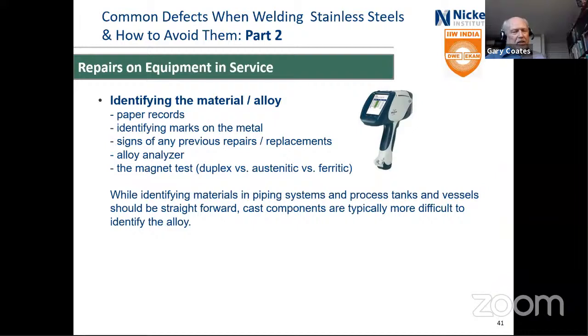And especially with cast components, a lot of cast components don't actually have a standardized grade name on them. They'll usually have the manufacturer's name for a particular cast material on it. So you can spend a lot of time trying to find out what the actual composition is, and therefore what the proper filler metal is. But the alloy analyzer, if you have one, use it. Get somebody in to do that.